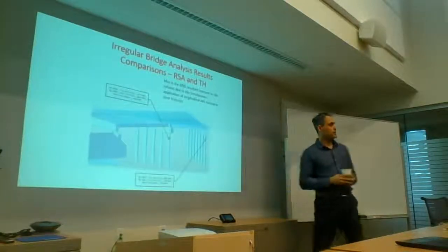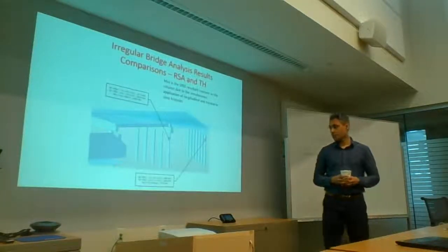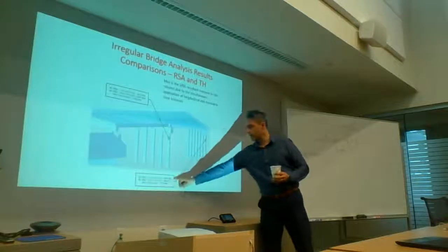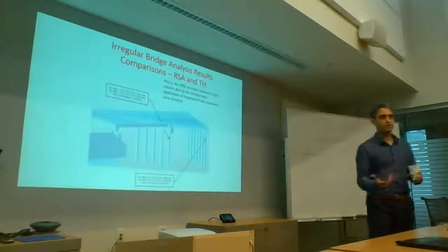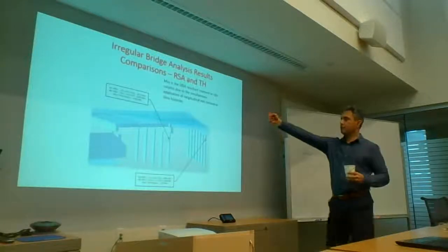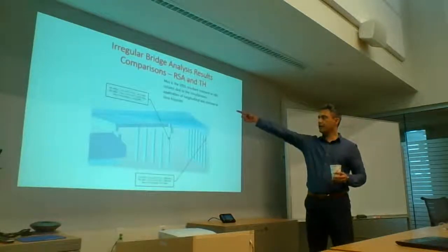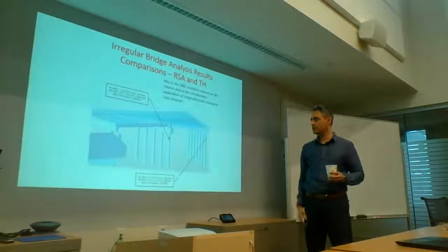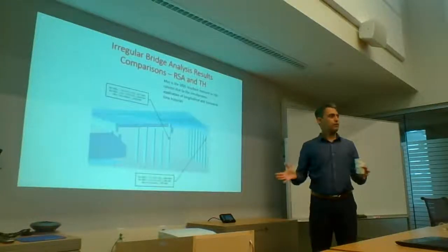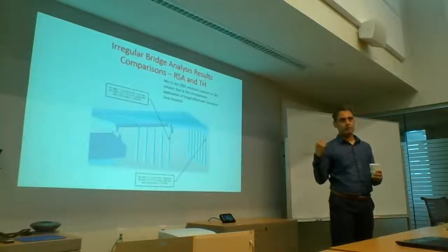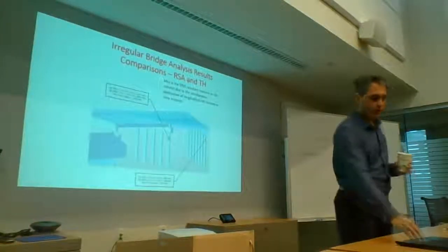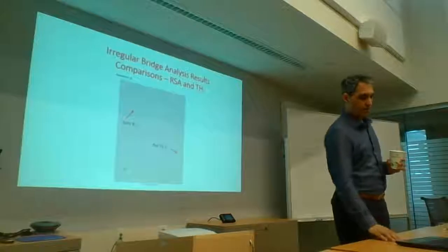There's a 15-20% difference, which is to be expected because this is real time and this is based on all those directional combinations and modal combinations, right? Up there, you're hitting a maximum of 3,900 and a time history of 4,000. So this is the kind of correlation you're going to get. You're never going to get the same answers, but you just want to check if you're in the ballpark in terms of just your linear stuff.